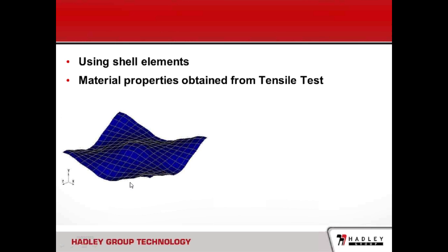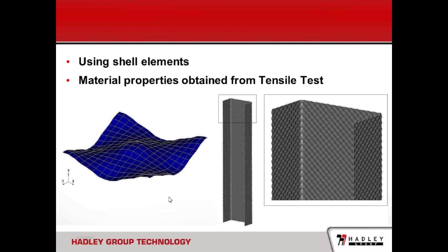But for many applications that have very large dimple products, we do another simplified approach, in which we obtain the mid surface from the dimple 3D element that we created previously, and by this way we can present this mid surface as a shell element that significantly reduces the number of elements, but still accurately presents the shape, the geometry of the dimple. Then we use this generic shell element to develop the large dimple strip and then roll-form it into a section.